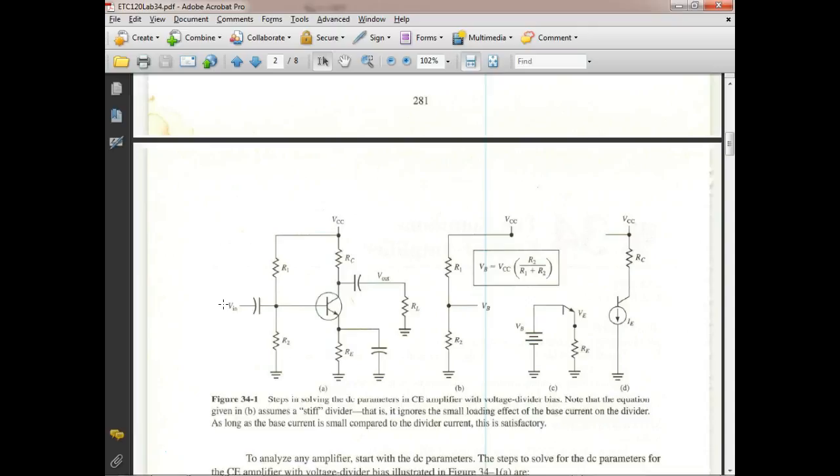But I had more than one person answer the ripple frequency, when normally loads don't see the ripple frequency, they see the watts out of the power supply. So this thing right here says nothing about input frequency, it says nothing about output frequency. It gives me an input voltage and gives me a watt. It gives me an output voltage at a current. Right? Now how did it get that? Is it full wave, half wave? You don't know. In fact, this is a switching power supply.